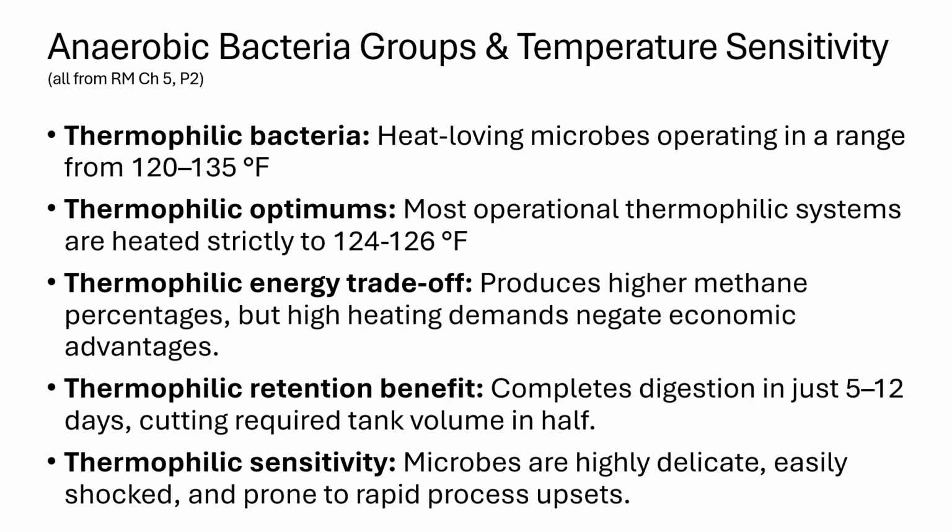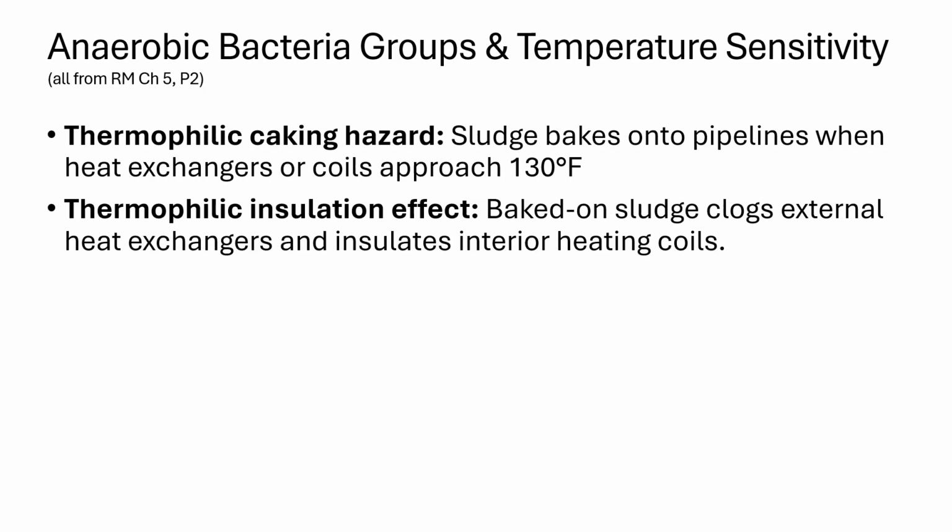Okay, so there's trade-offs. We've talked about the psychrophilic. That's the septic tank stuff and the Imhoff digester. We're really not going to see it in our wastewater plants. We've talked about mesophilic digesters, and those are great for cogeneration if you can force that digestion, but it's a long time to digest the sludge. And then we can look at thermophilic, which we have to pour energy into, but it's an extremely efficient digestive process. But again, it is a delicate balance here, okay? We can cause a digester upset with this, okay?